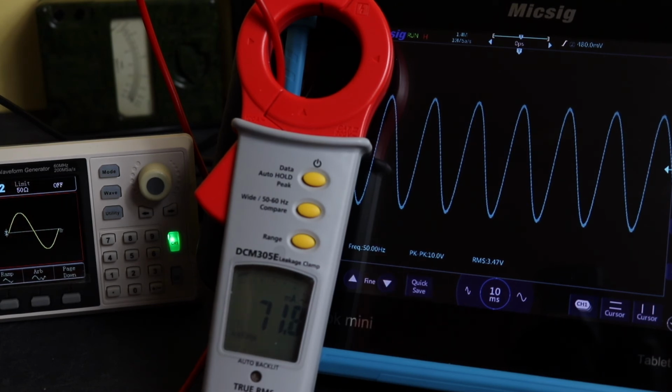If you don't do that, then the output voltage that you put on there may not match what is actually coming out across your load. As I say, I believe there's also some form of a current limit acting on this. That's the most that I can seem to get out, irrespective of whatever configuration I have of the load limit on this, unless I take this below 50 ohms.